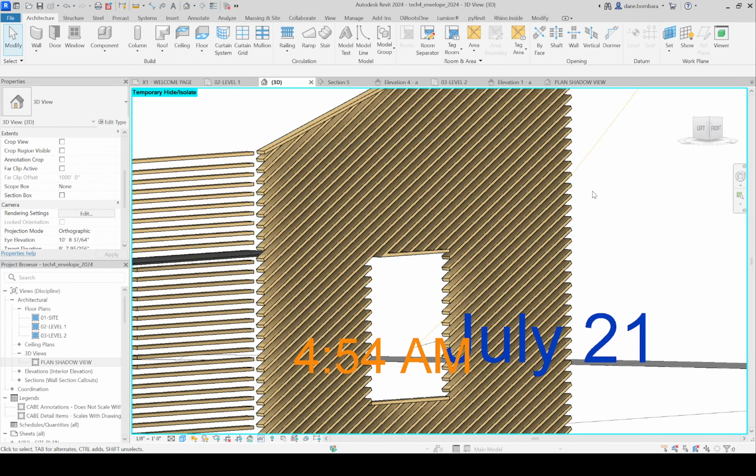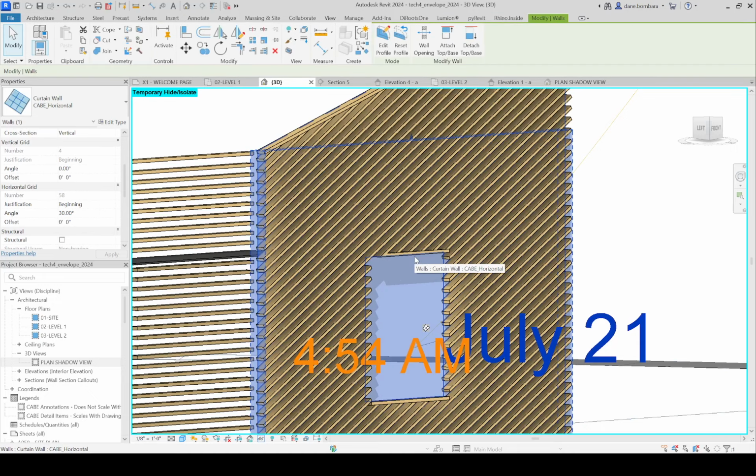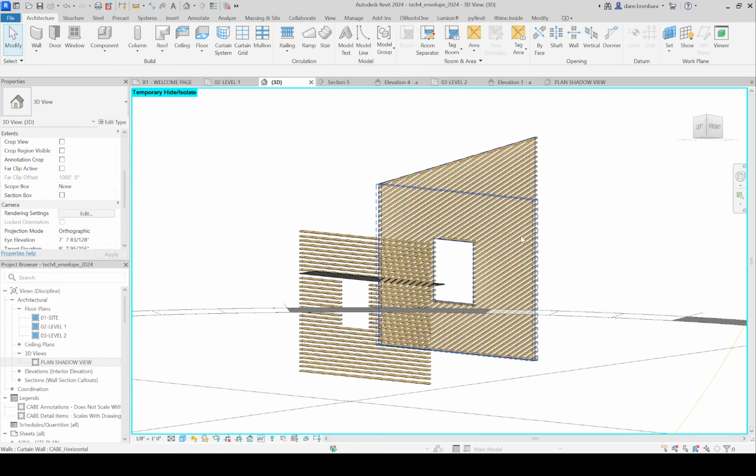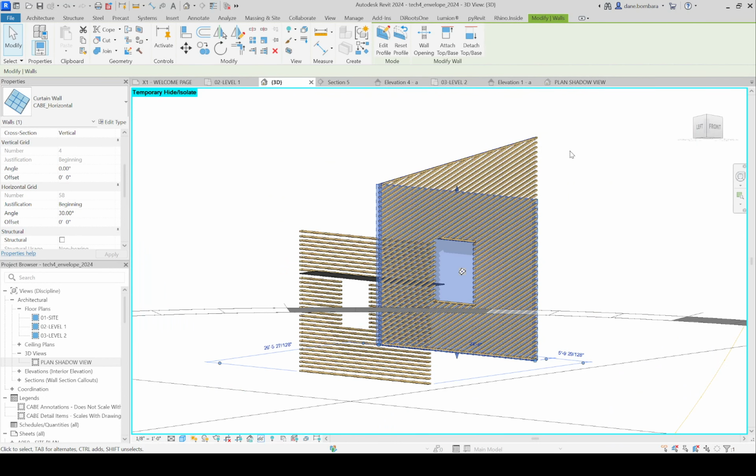Sure. I want not a 2x6, I want a 2x12, not a standard size in the library. And I want them to be, this would be good for very tight or small louvers, or if I make them deeper, I can spread them apart and get more view in between. So let's say take out every other spacing, 12 inches apart, make them 12 inches deep.